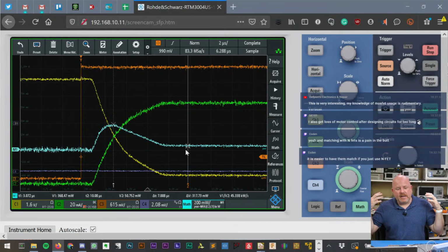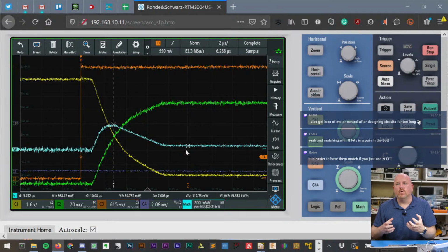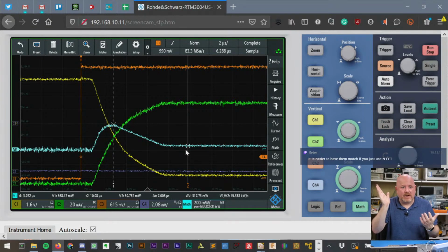So as a cliffhanger, the next measurement I'm going to make is to change the resistor to something more reasonable, because here we've compared 0 ohms to this, which is currently 3K, which is way too much. It just happened to be what I had when I soldered the circuit board. But the next step would be to put a 10 ohm resistor in here and see what that looks like, because now we're starting to get into more of a realm of what is an appropriate value.